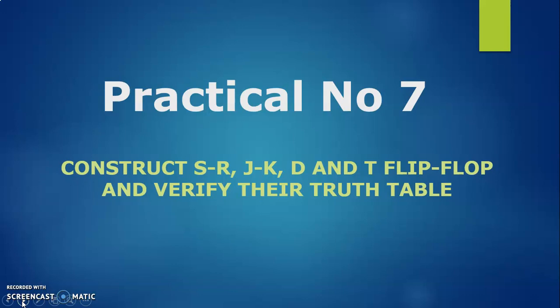So we have a 1-bit memory cell. The flip-flop is also known as a basic digital memory circuit. It has two stable states, namely logic 1 state and logic 0 state. We can design it using either a NOR gate or a NAND gate. A flip-flop can be designed using the fundamental circuit where NAND gates 1 and 2 are basically acting as inverters. Hence this circuit is called a cross coupled circuit.